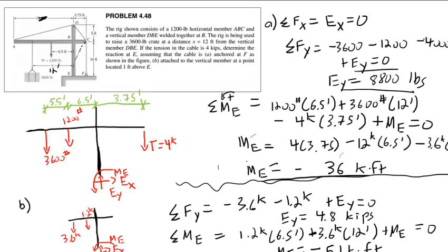Yes. Since this is a rig, you probably want a big reaction moment, right? So it can pull heavier. No, I mean the reaction. The question is, hey, this is a rig. You want a big reaction moment, right? Well, no. Ultimately, you want as small a reaction moment as possible. Yes, if you have a bigger load, that simply means you have to carry a larger reaction moment generally. But always, the bigger the moment in that connection, the more steel it's going to take, the heavier that connection is going to be. So I have a hard time saying that a bigger reaction moment is a good thing.